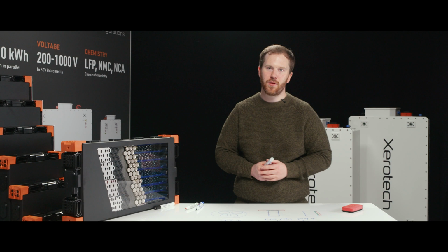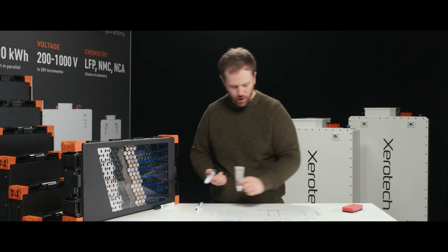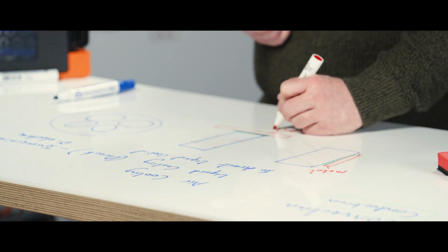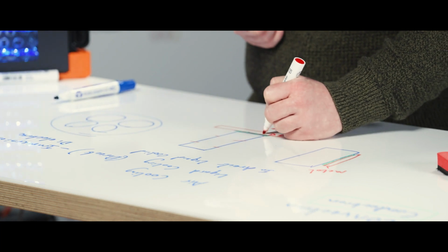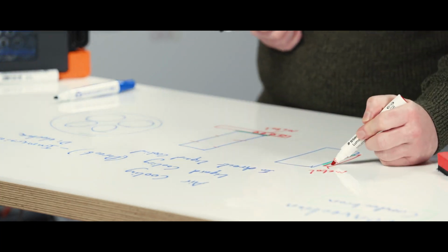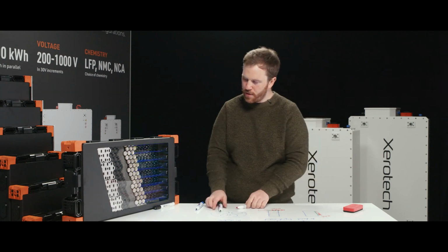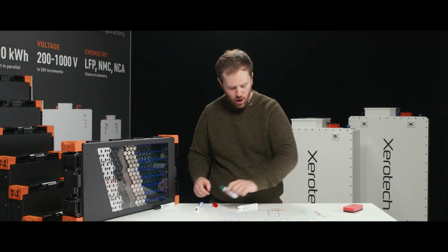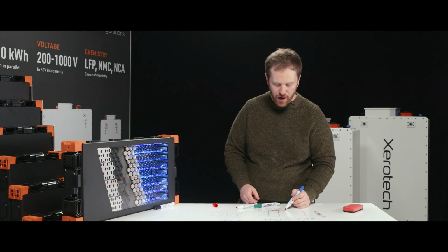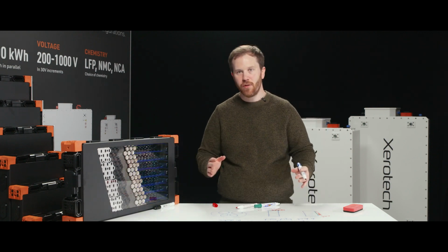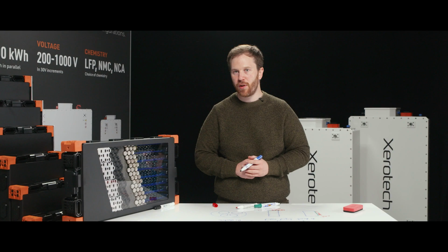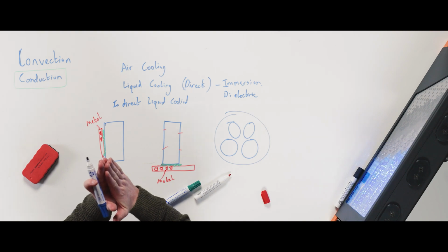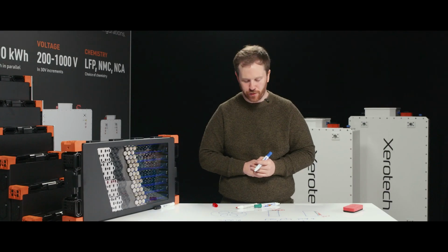Xerotech is a little bit different to these two. The vast majority of the market are using a metal heat transfer system, a duct or a pipe with little holes inside it, where we pump the coolant through. Xerotech, as you can see beside me here, uses a very thin plastic duct. In all of these cases, the metal has a very high heat transfer capability, on the order of hundreds. The thermal interface material is on the order of 1, 2, 3, or 4, because it comes down to the thickness of that insulator. A thin insulator means higher heat transfer flows through it.